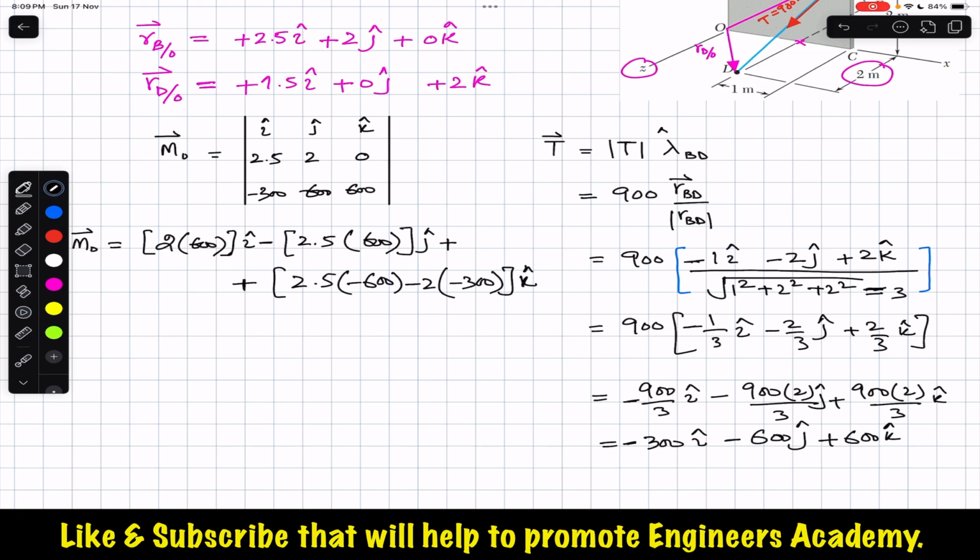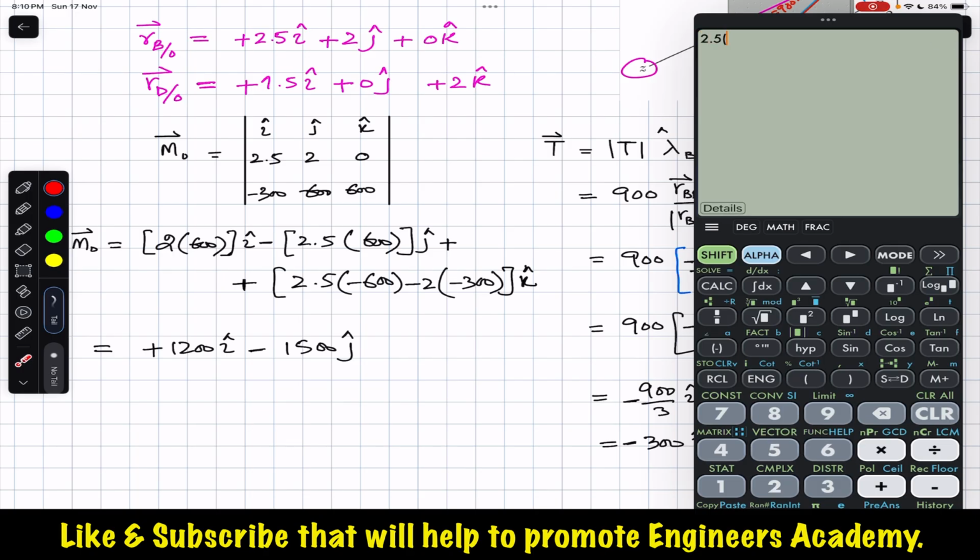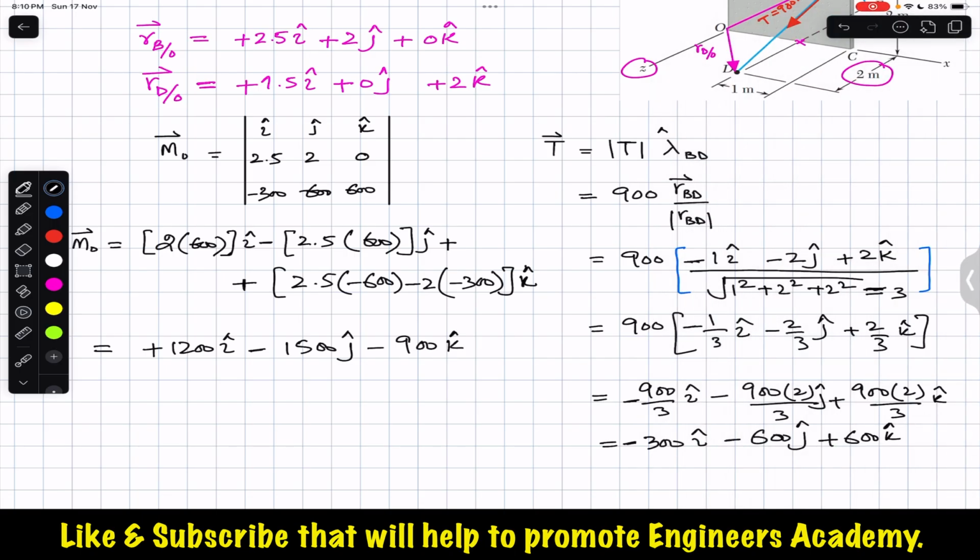This is into k. Now if we simplify this, 2 into 600 is 1200, so this is plus 1200 i. Minus 1500 j, since 2.5 into 600 is 1500. And here, if we evaluate 2.5 into minus 600 minus 2 into minus 300, this is minus 900, so this gives us minus 900 k. So now the moment about point O is this Cartesian vector.